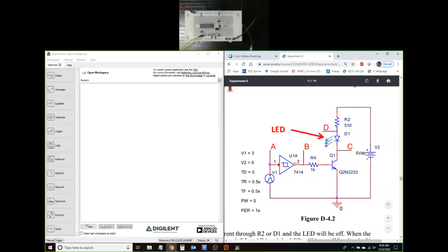That particular voltage source goes into a Schmitt trigger based inverter. It is going to have two threshold levels, an upper threshold and a lower threshold, and it is going to invert that triangle and give you a binary signal, a square wave looking signal, which is inverted with respect to the triangle, with two threshold levels. And by doing this experiment, we need to find out what those threshold levels are going to be.